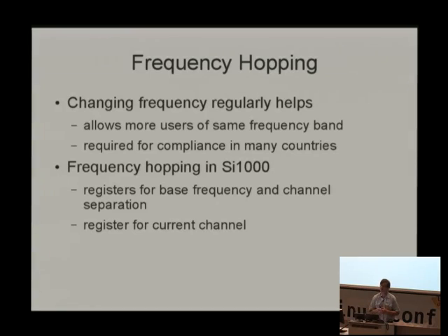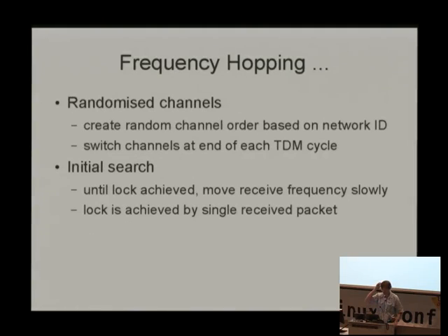You can frequency hop at kilohertz if you wanted to, though we don't hop nearly that fast. We typically hop frequencies at around 50 hertz or so. And so we're jumping between frequencies of that sort of order. Actually, we're often less than that. Depends on what bit rate we're running at. Okay, so that's basically frequency hopping and TDM. Oh yes, how do you choose your channels?